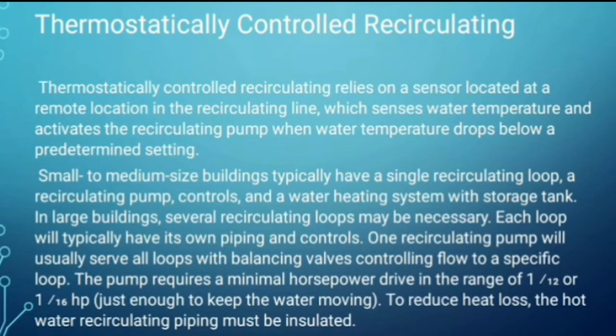Thermostatically controlled recirculating. Thermostatically controlled recirculating relies on a sensor located at a remote location in the recirculating line, which senses water temperature and activates the circulating pump when water temperature drops below a predetermined setting.